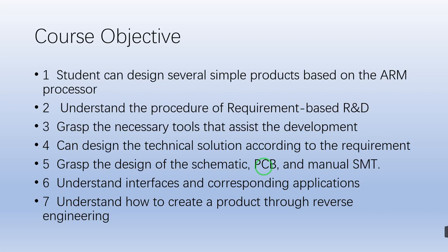Then after you have received those pieces of PCB board, you can debug, you can program and debug, and maybe you find there are some drawbacks in the schematic. Maybe some wire is disconnected or connected in the wrong direction. You can revise. So this is a kind of iteration process. In general, for each product, we will revise 2 or 3 times.